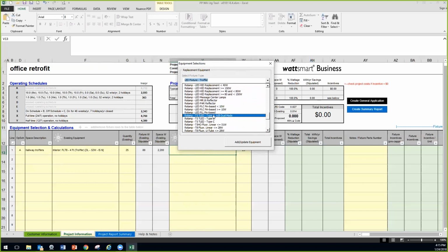So if you're doing T8 LED tubes, if you're doing a line voltage one, you're going to do a type B. If you're doing a ballast driven tube, you're going to do the type A. If you're doing an LED tube with a separate driver, kind of like a ballast, except not a ballast, an actual driver for that LED tube, you'll do a type C.